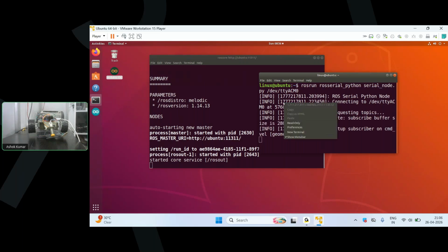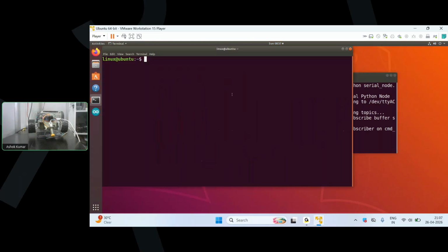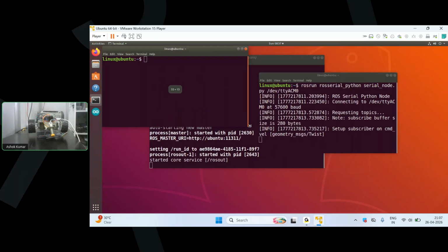Now, let's open the other terminal and there we need to create one simulator scenario, that is Gazebo. Gazebo is a simulator of ROS. So I'll try to open that. Also, I want one robot picture in that simulator. So first, let me export the model for that. A TurtleBot, I'm asking to create a burger shape on that Gazebo simulator.